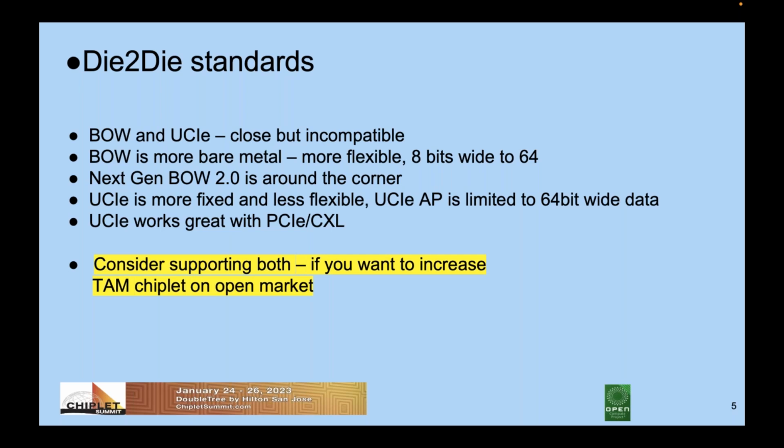Yeah, Kash, actually, I would like to concur with you because flexibility, sometimes it's good. From an architectural standpoint, I agree. Bunch of wires provides you that flexibility. From an open chiplet ecosystem, that's going to be problematic. Even the number of bits for support, like UCIe, when they mandated either 64-bit or 16-bit, at least when you pair it with another chiplet, even though you don't need the bandwidth, that is what it's going to support. Having that flexibility on the bunch of wires is good from an architecture standpoint, and as you mentioned, from a die to die standpoint, if you own both the two dies that you're pairing. But the minute you go to an open chiplet ecosystem and you end up with different chiplets with that flexibility, it's going to be problematic.